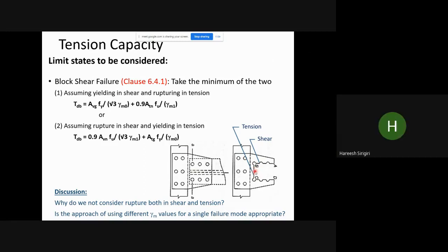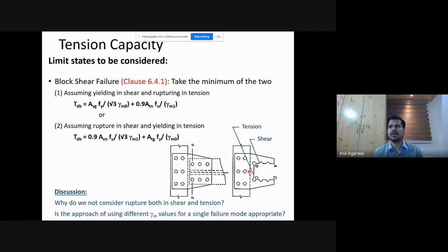To ultimate, sir. Yeah, so at least Fy; ultimate depends on whether you are able to achieve the strain hardening or not. But you are sure that at least Fy multiplied by this area, this much of resistance it will still offer after yielding also, right? Because it has not broken, it has not split into two parts. It is still able to resist a stress equal to Fy. Fine.